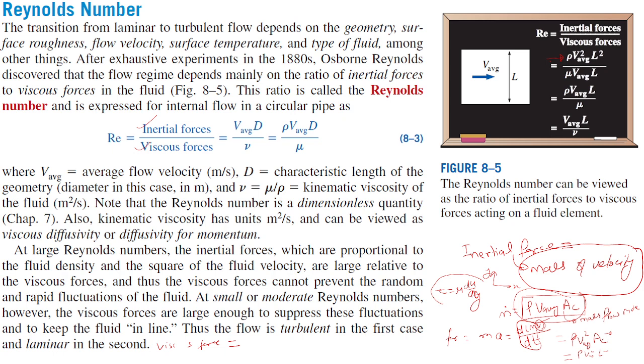So here this force is the shear force due to the viscosity. So here we use this term. Stress formula is what? Force by area. So force is this quantity into area. So let me put mu du by dy into area.